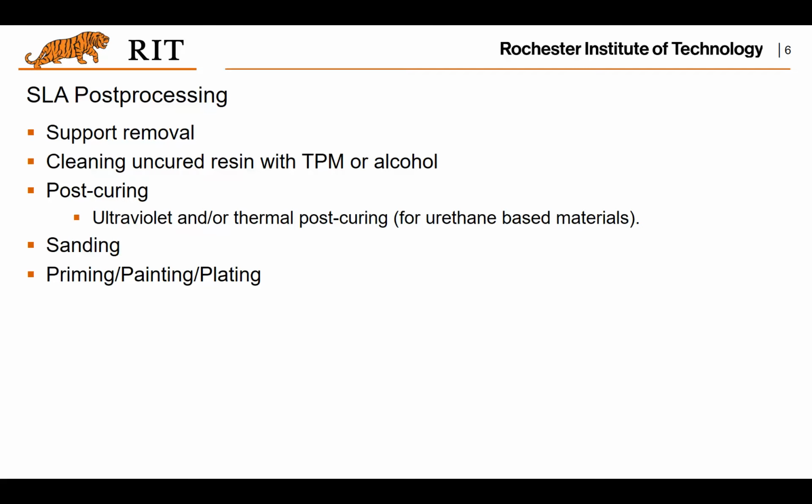Of course, you want to make sure how you lose the accuracy, and to determine if the part has shrinkage or not. If that's the case, when you do the design, you want to do some scaling up such that it compensates the shrinkage, just like what you did for injection molding. I mean, basically in injection molding, there will be shrinkage, right? But for this process, there is shrinkage as well, although it's not a thermal-based process. That's pretty much what I thought about for your second question.